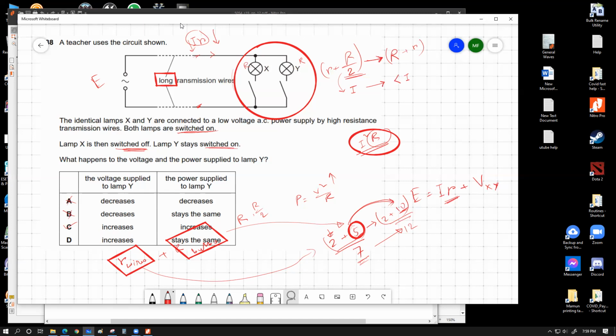জি স্যার, হ্যাঁ। এই পর্যন্ত বুঝা গেছে কিনা? জি স্যার, এই পর্যন্ত বুঝে গেছে স্যার। ওই জন্য আমি জিনিসটা বলতেছি এখানে যে আমাদের যখন দুইটা বাল্ব, when both of the bulbs were activated, switch was closed for both the bulbs, then if the current was I, I don't know this value, I'm assuming this as a number, then when one of the switches is open, because the resistance got increased, the new value should be less than I. I don't know what that value is, but the new value should definitely be less than I. এটা তো বুঝছো? Yes sir. এখন তুমি এই ইকুয়েশনটা দেখো, যে এই ইকুয়েশনটা খেয়াল করো। I এর ভ্যালুটা কমে যাচ্ছে, তাহলে এই পুরো প্রোডাক্টটা কমে যাবে না?